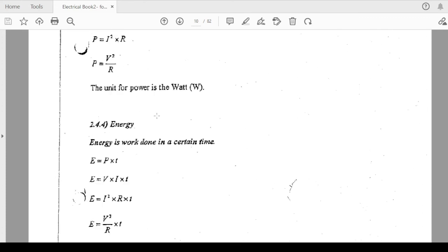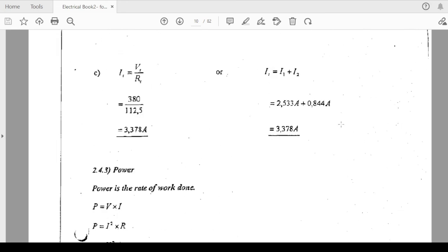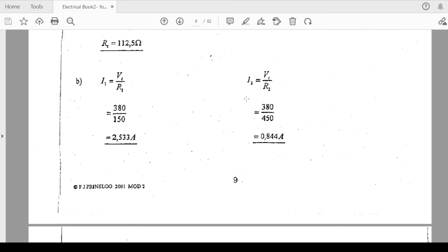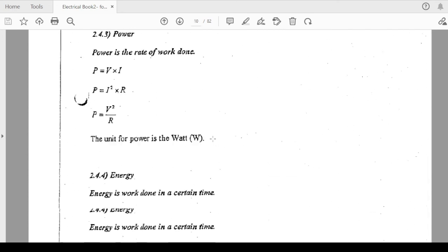What are we doing? We are calculating this formula, not power, current and voltage. Here, if I need current, I divide voltage by R. But if I need voltage, I multiply these two, I times R, to get voltage. So in the resistor of 50, they want the voltage. So you are going to say total current times resistor of 50. Then in the resistor of 150, it's going to be 150 times the current that you have solved as the total current, being that current is constant.